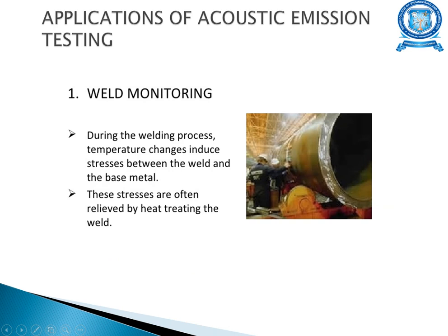So, applications of acoustic emission testing. First, weld monitoring. During the welding process, the temperature changes induce stress between the weld and the base metal. So this weld can be monitored by using this acoustic emission test. And the stresses developed due to welding are often relieved by heat treating the weld.